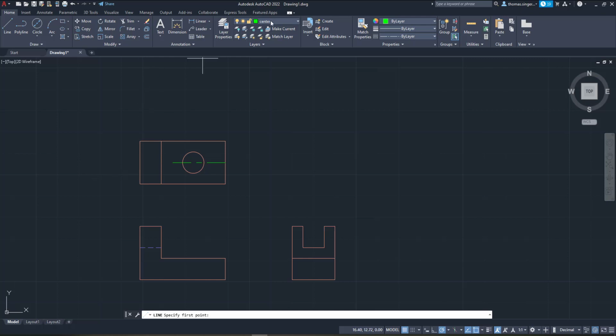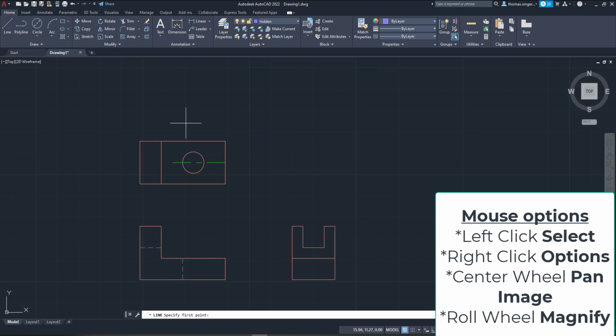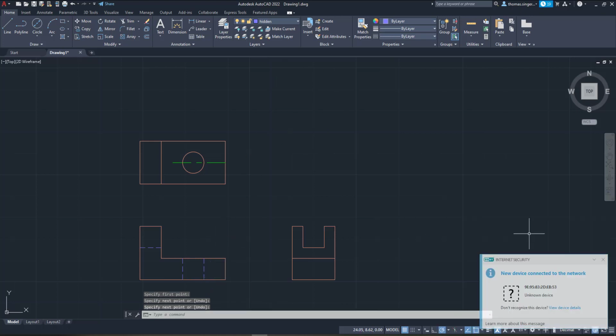Because that center line turns into a hidden line, so I choose the hidden layer, choose the line command, and the intersection of that circle and that center line becomes where the hidden lines are placed. And again, you can highlight, bring it straight down. Where that intersection point is, left mouse click, bring it straight down, left mouse click, and then hit enter.